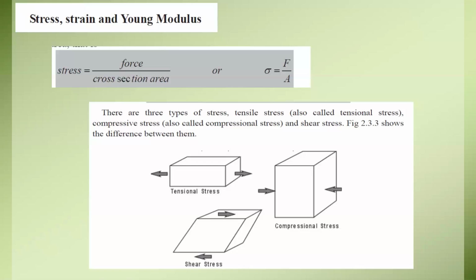When we want to calculate the stress, we don't take the component of the force. If this surface has an area of 2 meters square, and I'm applying a force of 10 Newton, what is the stress here? 10 divided by 2, I will get 5 Pascal. So we don't take the component. We just take the force and divide it by area.